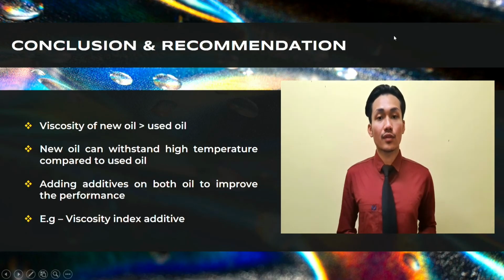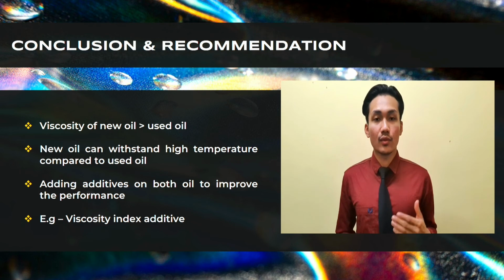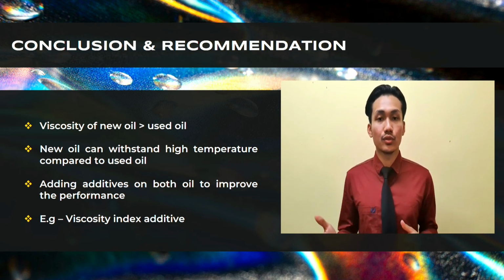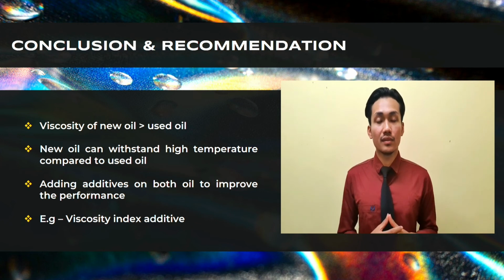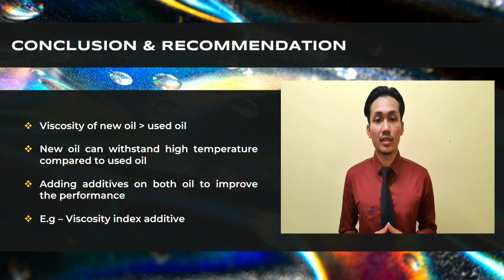To be concluded from this experiment, it can be said that viscosity of new oil is better than used oil, and new oil can withstand high temperature compared to used oil. I would like to recommend adding more additives such as viscosity index additive to the oil to improve its performance in terms of thickening the lubricant and ensure a more stable and consistent viscosity.